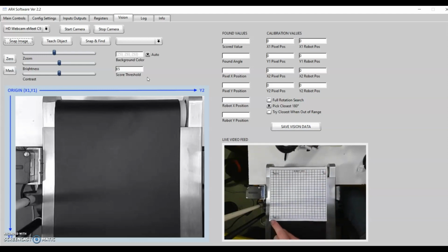I don't want any of those dots to fall on the silver areas, and the reason is when we teach these pixel positions they serve two purposes. One, for the calibration, but also for our background color, because when we go to mask out everything we don't want to see, it's going to grab those pixel positions, and grab the color there to choose our masking color.